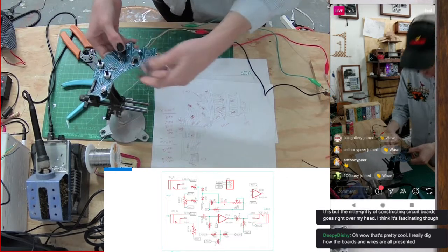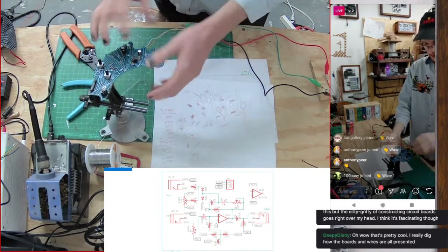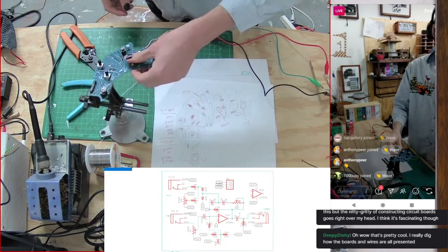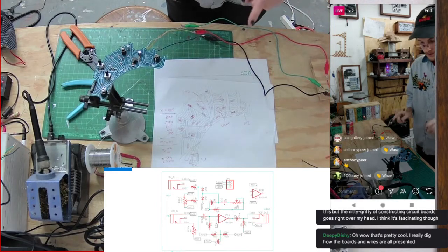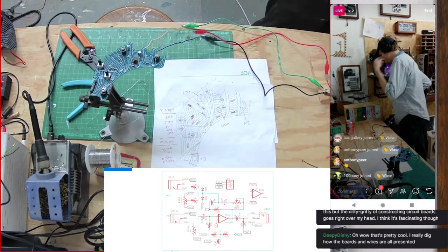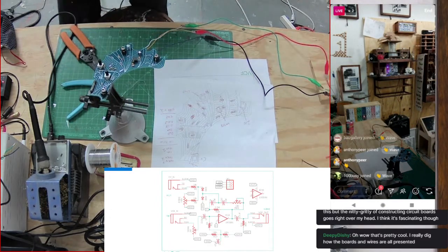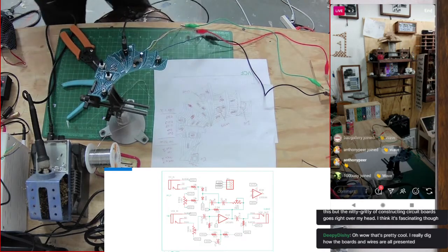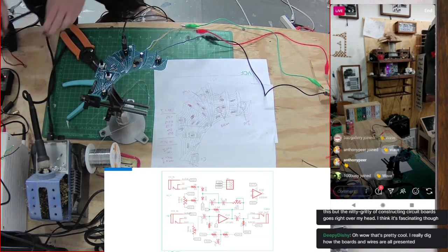It's not heating up. One thing that is a very clear sign that you've done something wrong with your circuit is if the IC gets really, really hot really fast. So I always check to make sure. But now what we're going to do is plug in some audio. I'm trying out a new audio setup this time. I have a very tiny little mixer plugged in with everything. So I'm going to go output up here. Input up here. Cool.